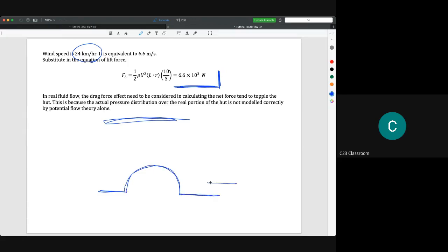So then we have a linear flow here. This linear flow will create lift force. Why? Because you know that the velocity is higher at this location. So higher velocity will give us a low pressure. A low pressure here means the pressure inside the tank is higher than the pressure at this location. So it has potential to be lifted. Okay.